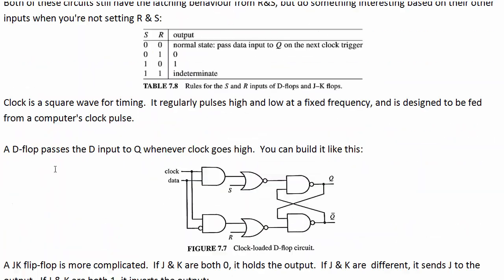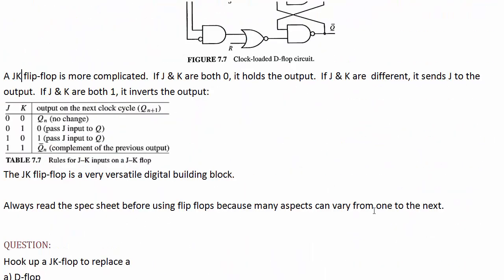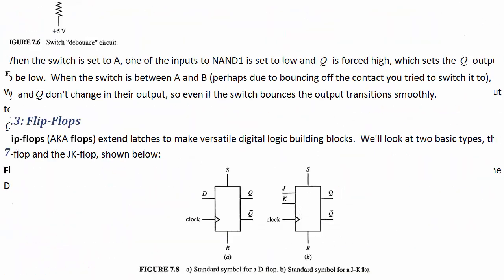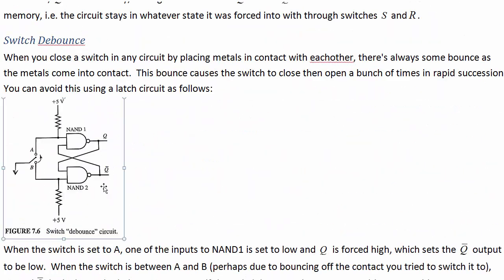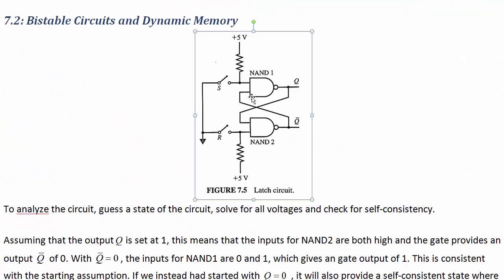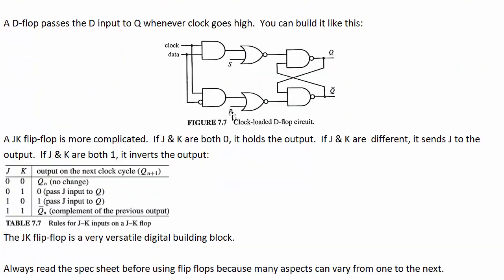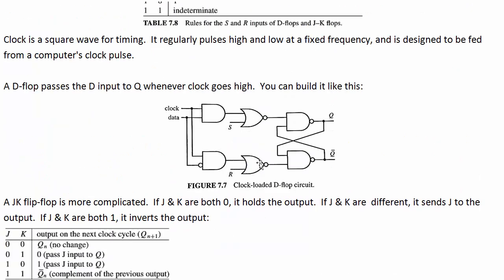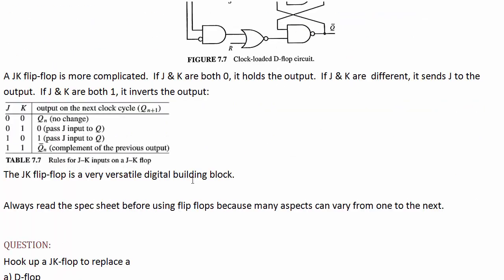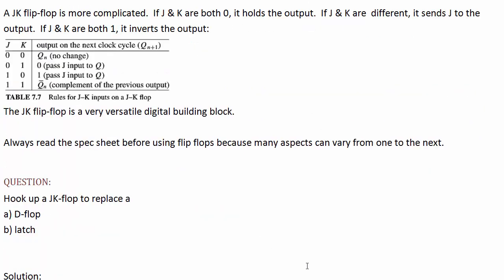This analysis notwithstanding, always read the datasheet before using a flip-flop, because a lot of aspects can vary from one to the next. For instance, we looked up here at the latch behavior, and in this early version of the latch, we had R and S operating when you put them to 0, but the flip-flops designed it when you put them to 1. So always double check things with the datasheet, just in case your manufacturer is doing things differently.